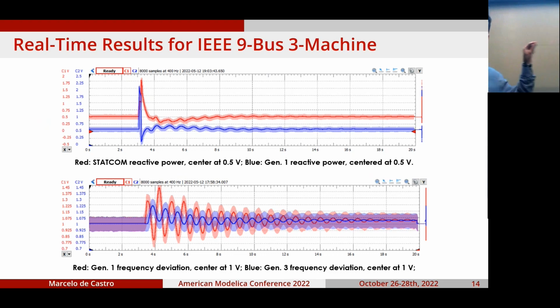And as you can see, you see a much broader pattern, and then you see kind of the average in the middle. That's basically the average and the noisy measurement. And this is what is important when you're trying to do, for example, a hardware-in-the-loop simulation to test your controllers and how they are able to reject noise.